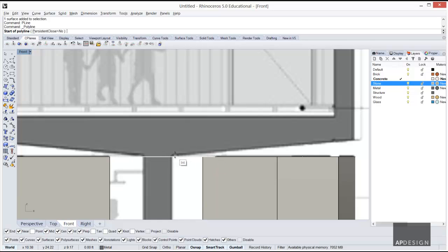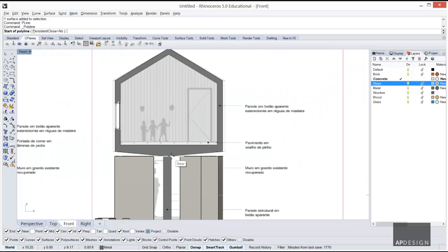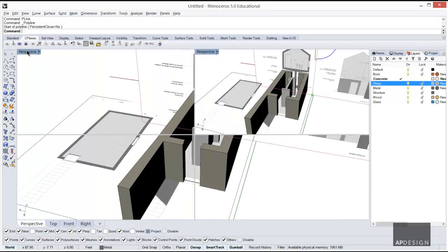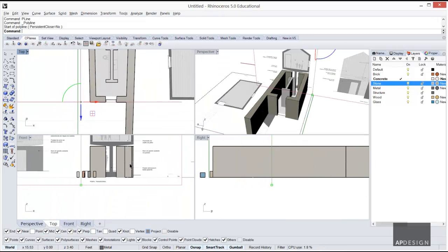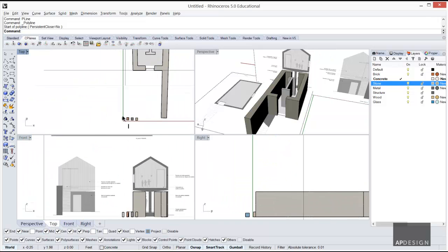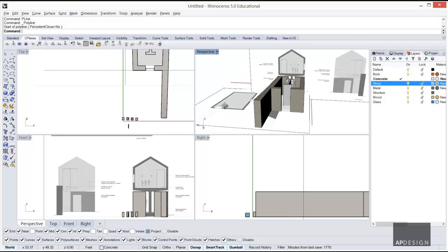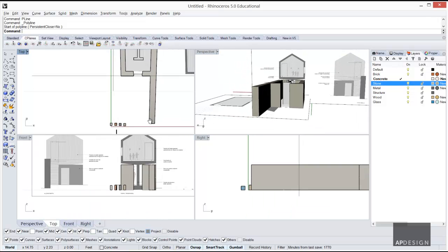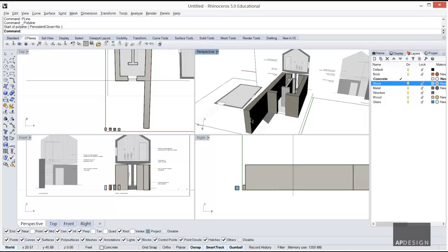One thing that you might want to do is use what's called project, and what that does is it makes sure that it can snap to things, but is drawing things on the picture plane. So if this is the origin for X, Y, and Z, when I hit project, if I'm drawing a polyline, it doesn't matter that I'm snapping to things up here.